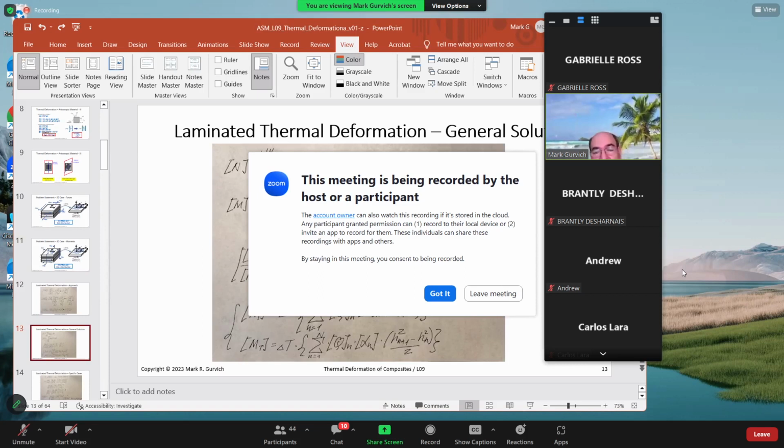And of course, integration goes from the lower side of the laminated package up to the upper. This is the reason I put minus h/2 to plus h/2, if it's symmetric. If not symmetric, it will be within limits, but again through the entire overall thickness h. So if we integrate it, we will receive this equation, similar to what we had with stiffness. Let's forget for a second about this component, but this portion, you see my cursor, it's exactly what we had in the previous lecture, not on Tuesday, but last Friday, what we called classical laminated theory.